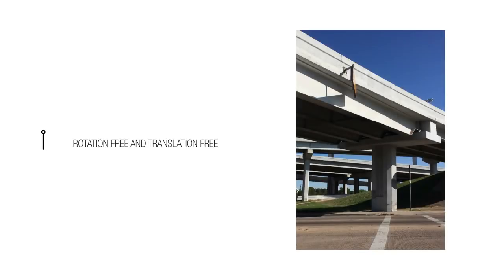You know what kind of works with this at this level? It's kind of rare, and it's not very common in buildings. We sometimes will see it if we have like a single column for a highway overpass. That may behave like something that is rotation free and translation free.